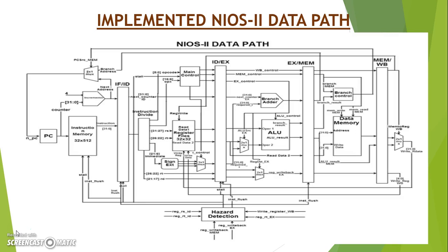The third stage is the execute stage. This stage generates the branch address, data memory address, results, and write back register address. The read data 1 from the previous stage is fed to the ALU. The ALU either generates an address of data memory or a normal result. The ALU gives out a branch result when the comparison is done for a branch operation. It performs operations such as addition, subtraction, multiplication, comparison, and logical OR operation.